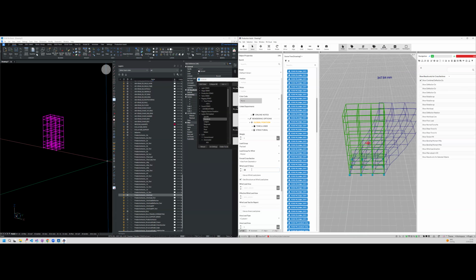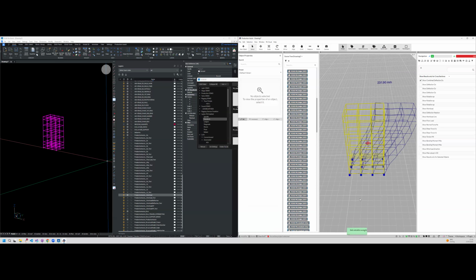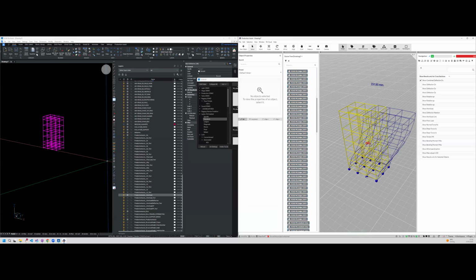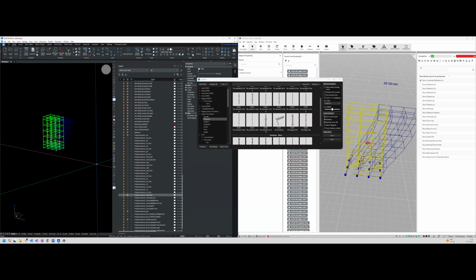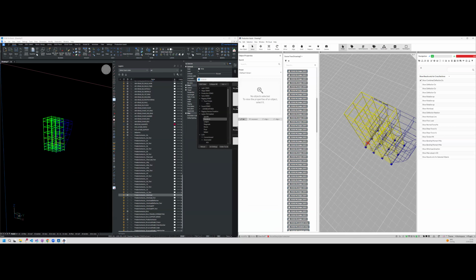You can change the CF value to 1.2 in here, and then you see that if this structure without any diagonals is inside the wind, you would end up with about 20 centimeters, I think that should be like 8 inches, of deflection to the side in this direction.